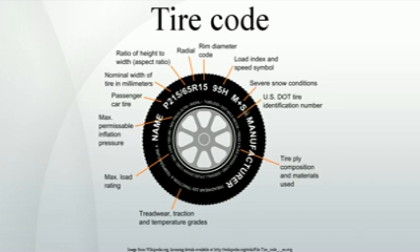An optional letter indicating construction of the fabric carcass of the tire. B, bias belt, where the sidewalls are the same material as the tread, leading to a rigid ride. D, diagonal. R, radial. If omitted, then it is a cross-ply tire.